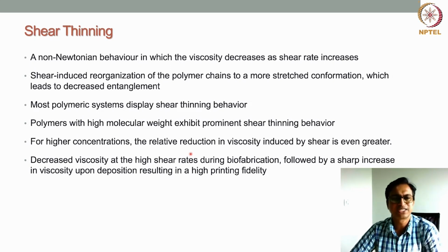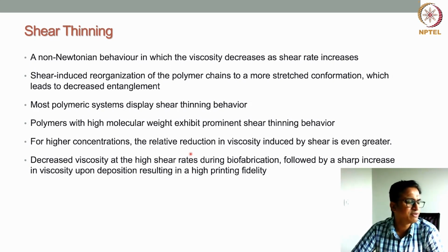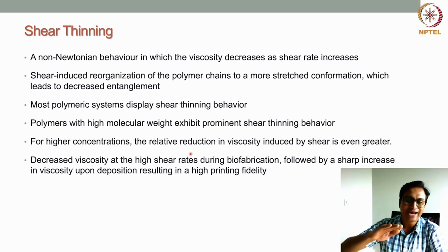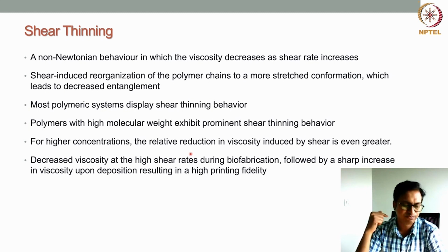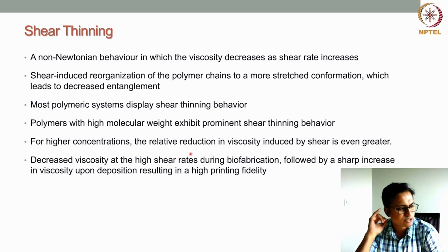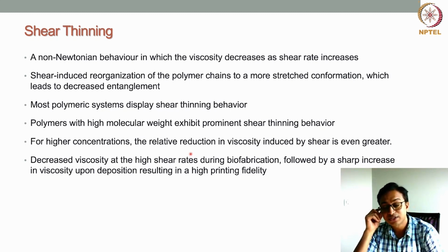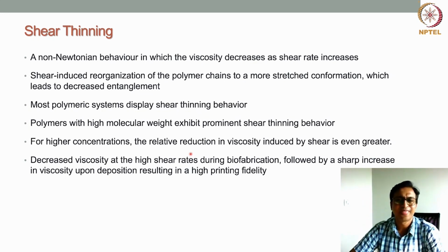The other thing, as we have discussed earlier, is that shear thinning is a behavior that is very good for bioprinting, because shear thinning is a non-Newtonian behavior in which the viscosity decreases as the shear rate increases. So with increasing shear rate, the viscosity decreases. And as you know, in our extrusion-based bioprinting, when we extrude the material, it experiences pressure or shear force, and the generated shear stress can cause damage. The high viscosity, because of this, the printing fidelity can also be good, because of the shear induced shear force, what it does actually,